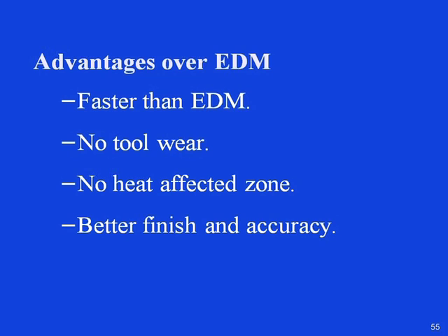No tool wear, no heat affected zone, which is very common in case of EDM. There will be a large heat affected zone in the cutting area in case of EDM. Also, better surface finish and accuracy can be obtained with respect to EDM in case of ECM.